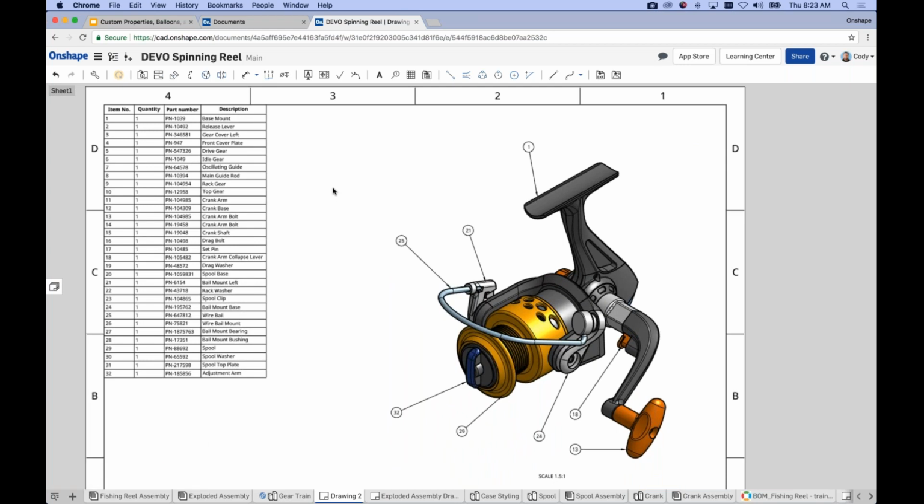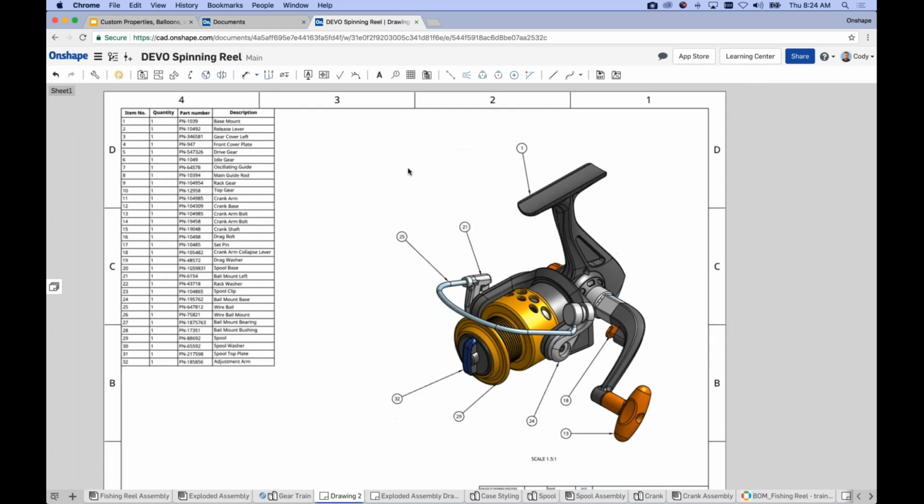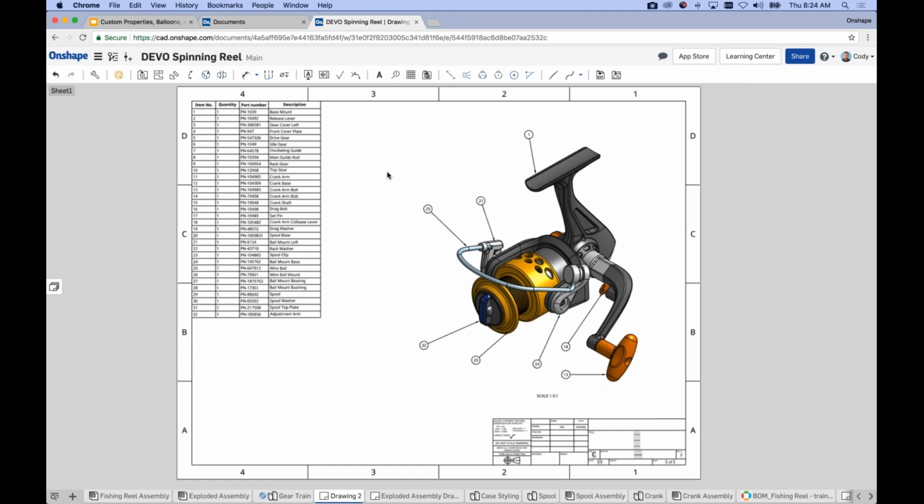And if you want to move things around in your assembly to reflect that, you just update your drawing to accommodate, right? And so you don't have to reassign balloons or re-enter BOM numbers or worry about things getting out of sync, if you're manually typing in balloon numbers and things like that. So again, just keep that in mind when we talk about parametric link, or actually associative, between the two. That's what we're referring to: the ability to update the assembly and go in and update the drawing.